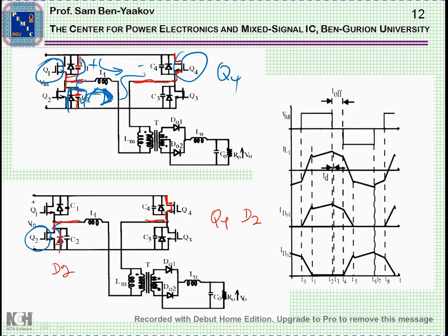So as you can see, this circuit is very clever in that it uses the transistors of the bridge itself to commutate the voltage, and therefore reduce the voltage on a transistor, say this one, before we turn it on. So it is a true zero voltage switching in this case.